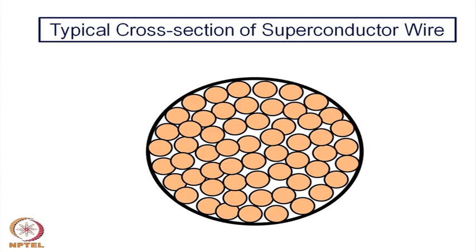So, even the low temperature superconducting wire strands are actually embedded inside a metal like copper. If you are talking about a silver cladded ceramic superconductor, silver also acts in the same manner. Silver provides that kind of thermal conduction which avoids any hot spots or thermal runaway.